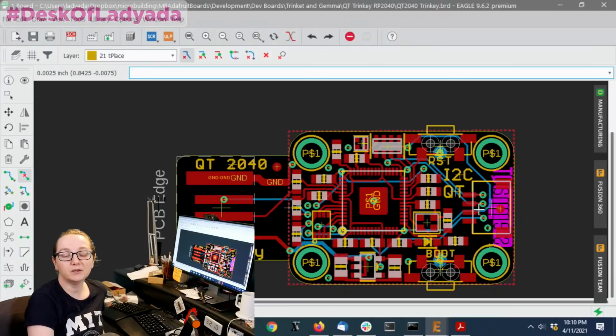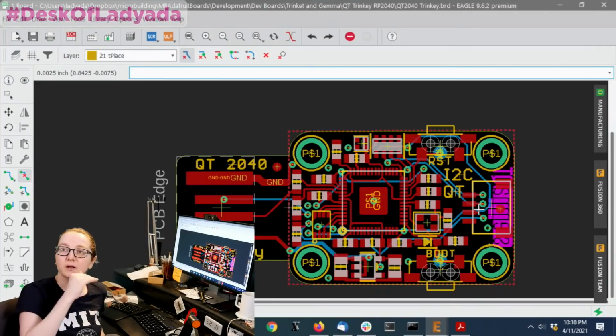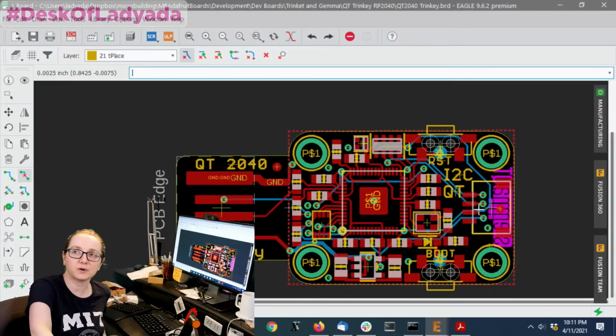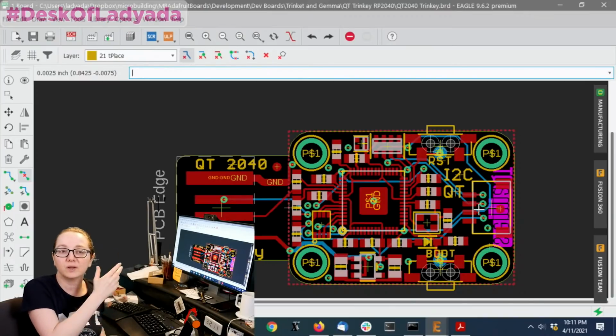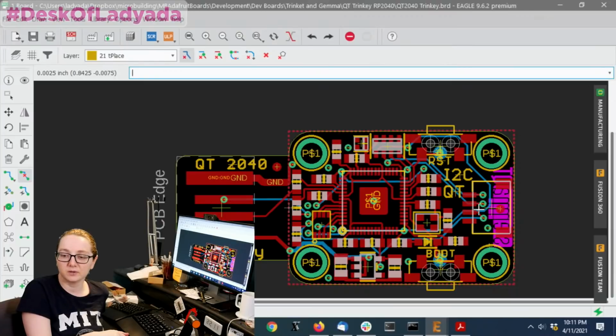For a lot of people, I would recommend using something like the MCP2221, which would convert it to something that Python can read. But I can see some situations where folks say, no, I really want it to spit out serial data, or JSON data, or they want it to come in directly into something like Processing or Unity, where you don't want to have a Python interpreter feeding data into it. You just want it to read. You can open up a serial port and read the data, but anything where you call a Python interpreter from it gets complicated. And I get that. There are people who want to integrate it into some C code, or maybe with web serial JavaScript. All these things would not work well over CPython running on the computer.